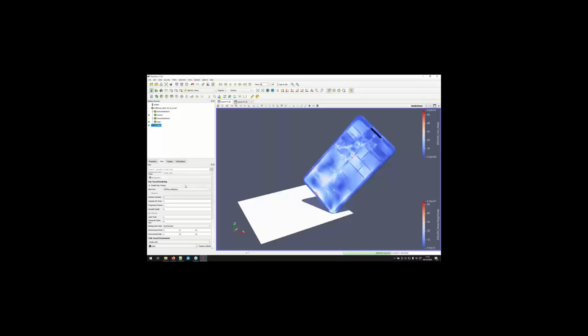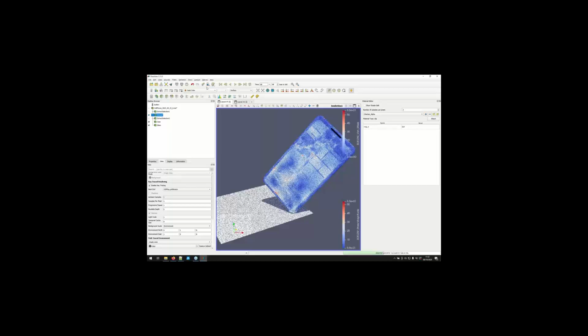So here we have, out of the box, lots of nice rendering, but this is by default either the color maps or the solid color. So one thing we will do is to add some materials to our parts. So materials means lighting materials. So we have the materials editor here, and you can activate the shader ball here, which gives you an insight of the selected material we will apply.